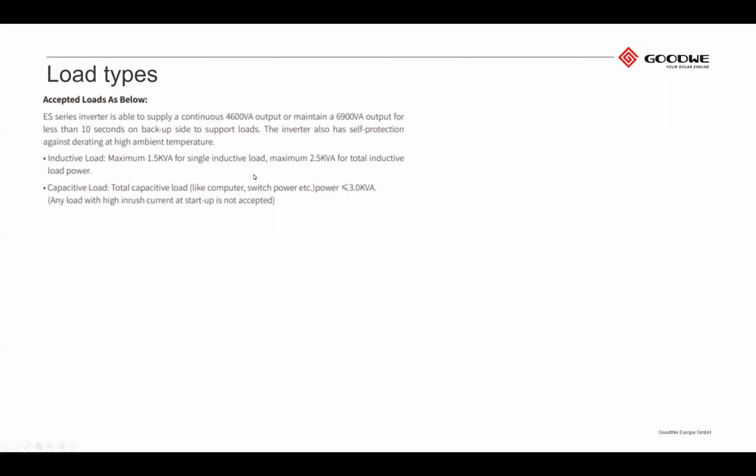So it's very important when designing systems to look at what kind of inductive loads these customers have. If they've got booster pumps, or things like that that they need to run on backup, it's important to make sure that the system is sized correctly for that type of load. One could also use a meter that has a very high resolution to measure the startup current draw of that motor. That is the best way of doing it, and then you can recommend to the customer that either he needs to install a better motor or have some sort of startup aid for his motor to make sure that it does not give that peak current draw.